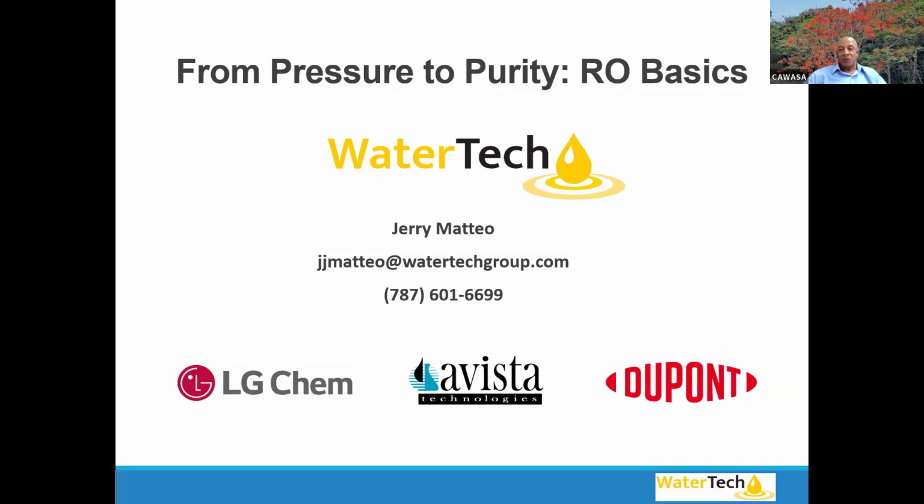Okay, we have a question from Roger Karim in the chat. He says, how does use of beach wells impact raw water quality? That's a good one. So, boy, it can depend. But what's nice about a beach well, what's good about them, is they usually have low turbidity. Because the problem you can have in an ocean intake is a storm. A storm could kick up so much turbidity you can't even run your RO, because your pre-treatment will be overloaded.